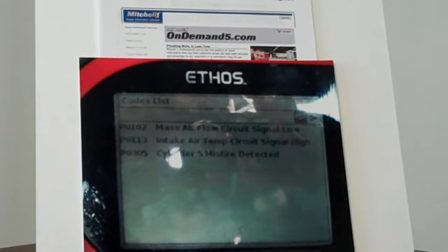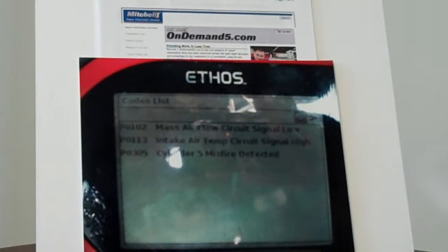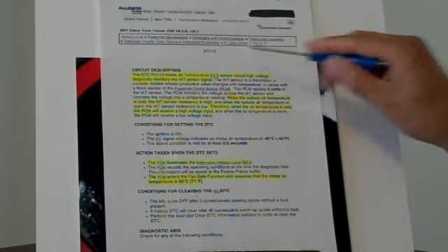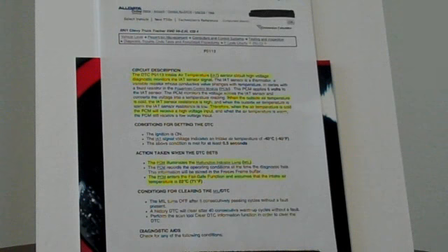This vehicle had 3 diagnostic trouble codes stored in memory. First, a diagnostic trouble code is a 5-digit code stored in the control module's memory that specifies a component or system malfunction. Diagnostic trouble code P0113. The intake air temperature sensor registered a high resistance due to being left disconnected and unable to reach normal operating temperature. Step 6 in the pinpoint test says to check for a faulty electrical connection at the IAT sensor. Problem found and fixed.